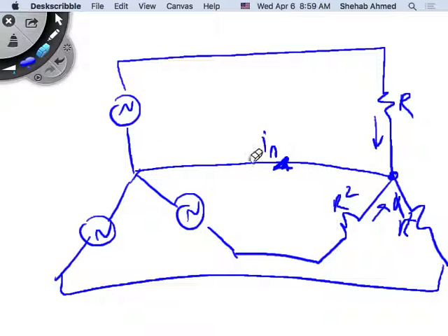And if I detect current flowing in my neutral, I know that I have an unbalanced system. I can do that by looking at zero sequence quantities. If I have I0 not equal to 0, right, after I look at how to take from my phase quantities and calculate my zero sequence quantities, actually we did that for the zero sequence.